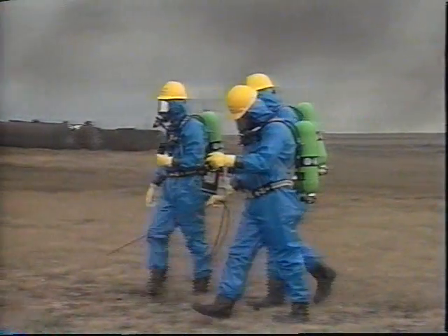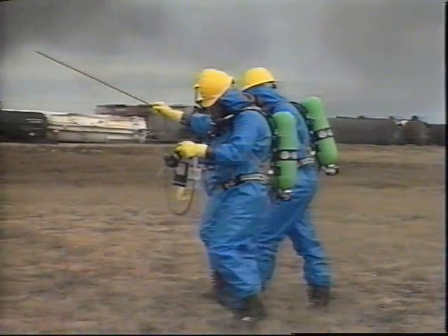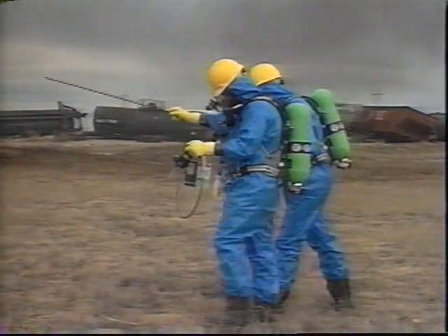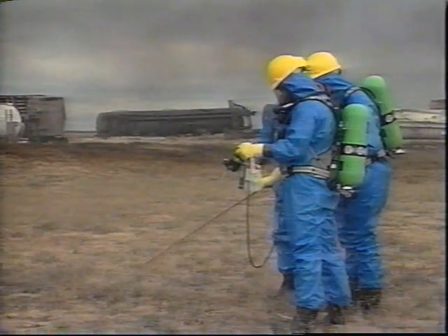Unlike air sampling devices, which are used to collect samples for subsequent analysis in a laboratory, direct reading instruments provide information at the time of sampling, enabling rapid decision-making. Direct reading instruments may be used to rapidly detect flammable or explosive atmospheres, oxygen deficiency, certain gas and vapors, and ionizing radiation. They are the primary tools of initial site characterization.